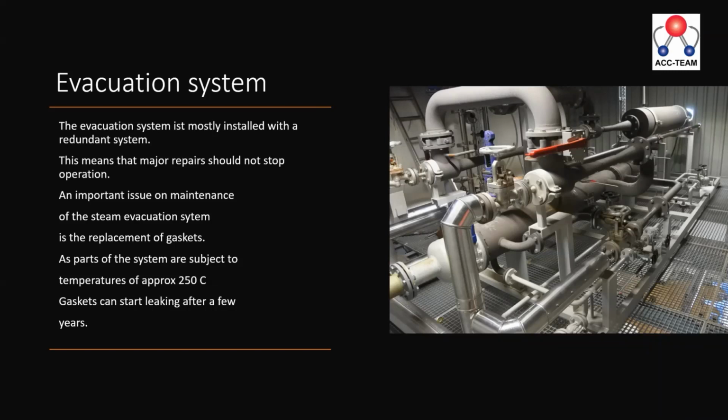Maintenance on them is relatively simple. The most important items that can start leaking are the gaskets. The ejector nozzles themselves are nowadays very seldom wearing out. With every maintenance exercise you should check them, because you can have some erosion, but the most important thing is the gaskets, because the unit is locally heated up to 250, 300 degrees C. It expands. Then after a while, you switch off, you go to the other one, and it cools down again. That thermal movement is damaging your gaskets.